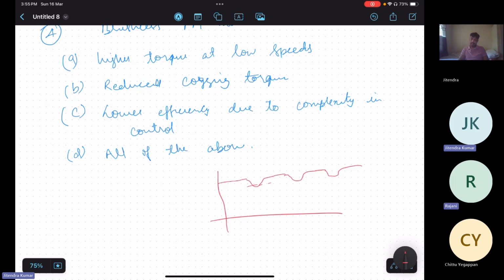But on the other hand, with sinusoidal, why is it happening in BLDC even? I am talking about BLDC, because its characteristics will be more similar to a DC motor, because we have commutation at every 120 degrees. We are switching our current, giving current and making it zero. Now the next phase will start operating from here, like 120 degrees.